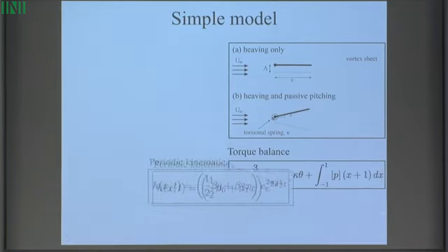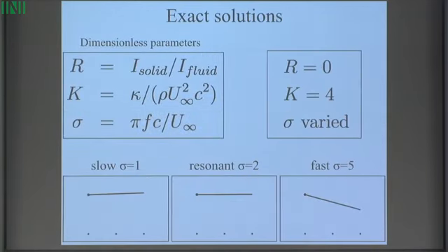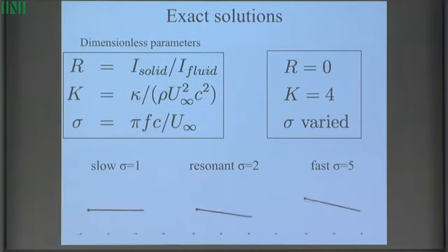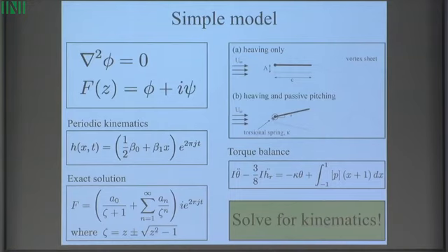You probably missed how the Kutta condition was enforced, but it was the form of this solution here in the mapped domain. There is a singularity at the leading edge, which is a real singularity, but there's no analogous singularity at the trailing edge at +1. And so that is the Kutta condition. You enforce finite velocity at the trailing edge. So that's how it's enforced in the theory.